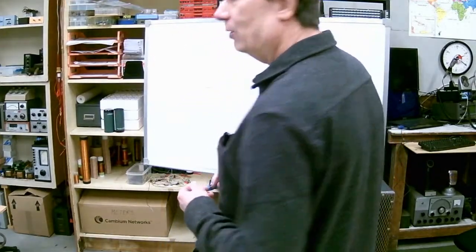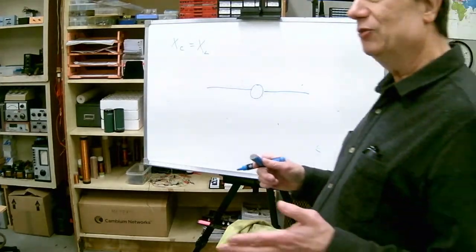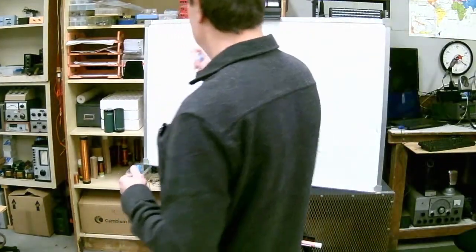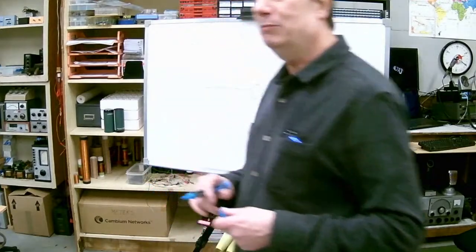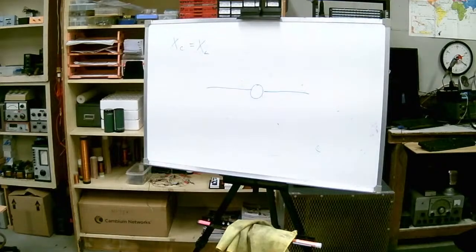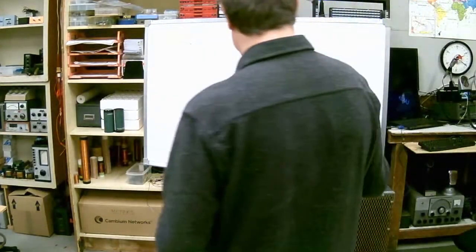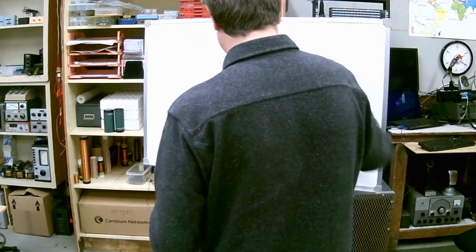We've always assumed that the antenna is resonant up to this point. It follows the same rules. If we look at the impedance at the feed point, we'd find that the inductive reactance and capacitive reactance cancel out exactly. Now, what happens if you get an antenna shorter than a wavelength? What does it look like?